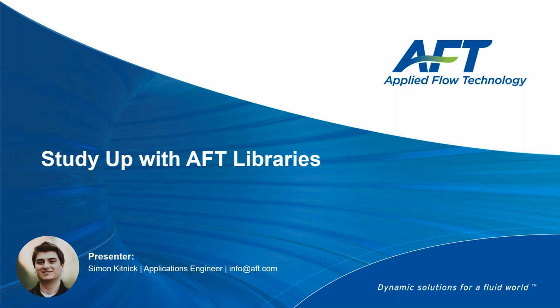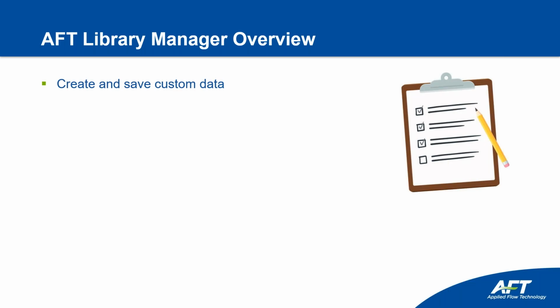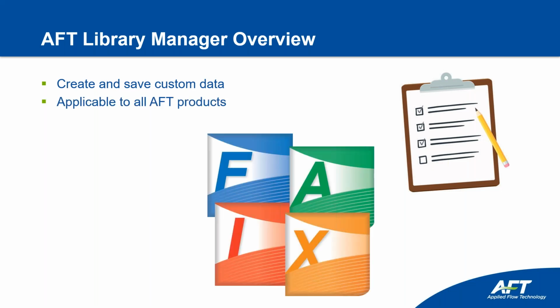Today, we're going to do a little studying up at the AFT Library, and we're going to learn all about the Library Manager feature and how to effectively use it in the software. The Library Manager is used to create and save custom data within the software. Today, I'm primarily going to be showing you this in Fathom and a bit of Arrow, but the Library Manager is applicable to all of the AFT products.